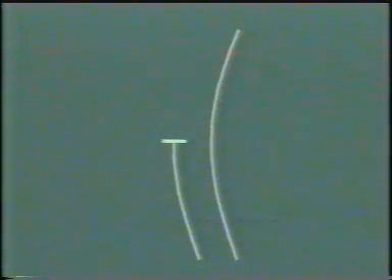This is analogous to the comparison between a pin-ended strut, corresponding to the simply supported beam, and a cantilever strut, corresponding to the cantilever. This correspondence is not exact, as the behavior of beams is more complex, as it also involves torsional effects. The end restraint provided to a beam has a major influence on the occurrence of instability, and can be utilized to enhance the load carrying capacity whenever instability is likely to occur.